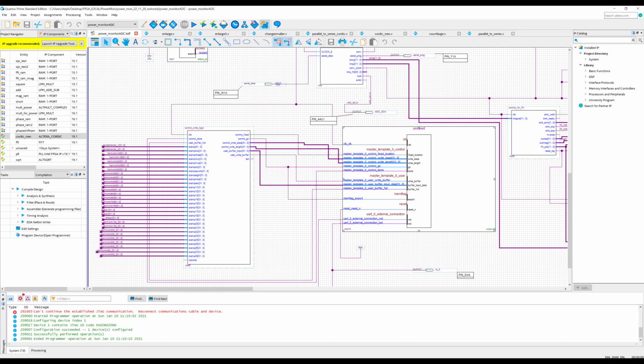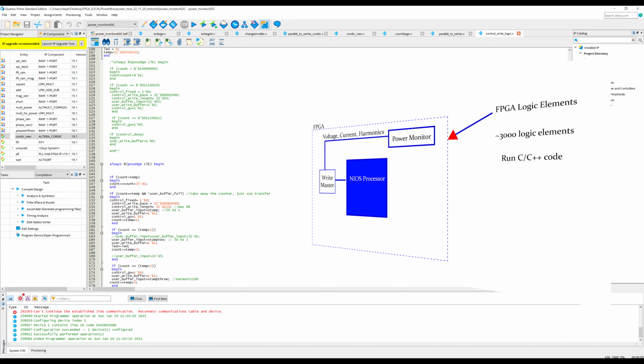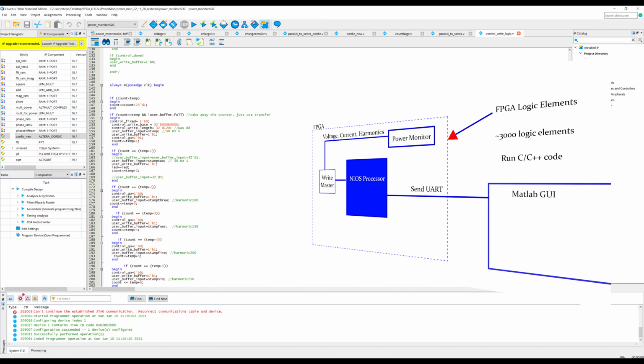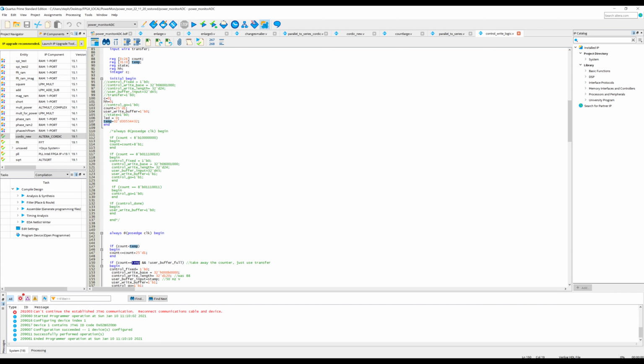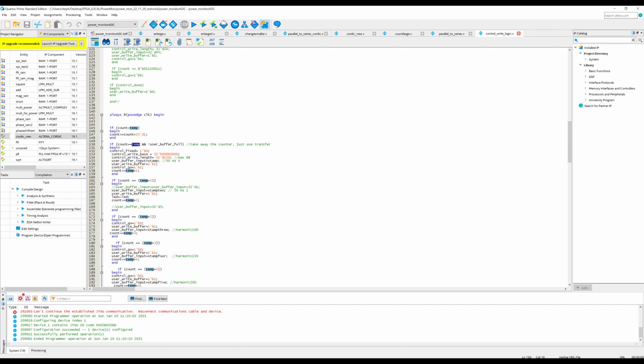Let's now move on to addressing this interface code. So let's take a look inside this write logic. Again, it's another fairly large Verilog module here, but the important stuff is in this always block. You can see this code will be executed when the count reaches a particular value, and that value is stored in temp. It's quite arbitrary actually. I think about once every half a second I will input the next round of data into the embedded processor. So that's why that's there.